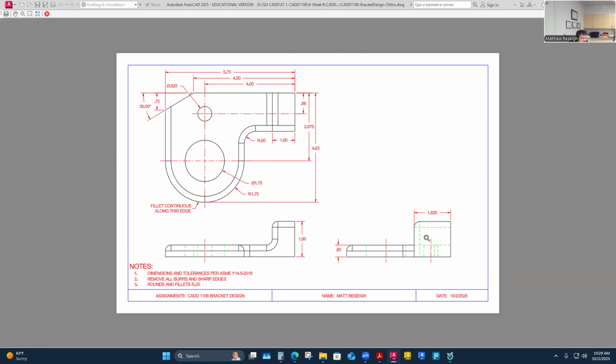Plus, I've even used them as dimensions. For the one you dimension by yourself, you might find that there maybe is a view that you don't need, and that is true. I gave you three views to dimension, so you can choose to use them or not. Or like this, you could place one dimension on it if you need to, but you don't have to delete one of the views. A few people that I've seen upload it probably were able to get most of the dimensioning in the top and front, and it was questionable whether we needed the right side view in that base mount part that you'll dimension. But just use it. I like it for clarity, and usually if I have a view for clarity, I like to put a dimension on it. Otherwise, I feel like it's almost worthless.